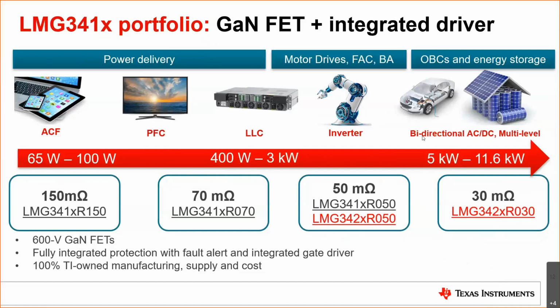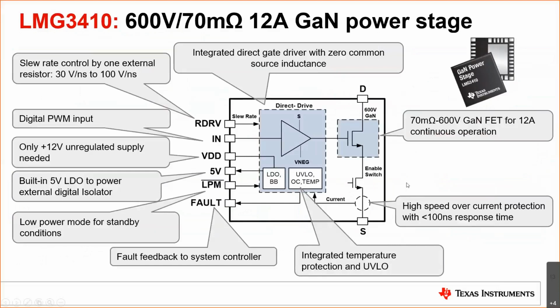But now let's have a look at our GaN devices in particular. I teased you already up front a little bit, you get way more than a standalone FET. And that's what you see on the simplified block diagram. What Texas Instruments does is integrate the gate driver next to the GaN. That brings some advantages that we will discuss in a second, but certainly from a design aspect, it's a very easygoing implementation. From the input side, you can work with a normal digital PWM input, so you do not need any additional gate driver.